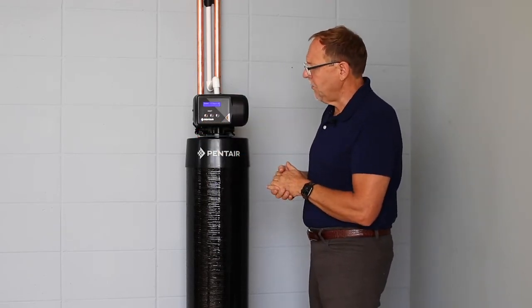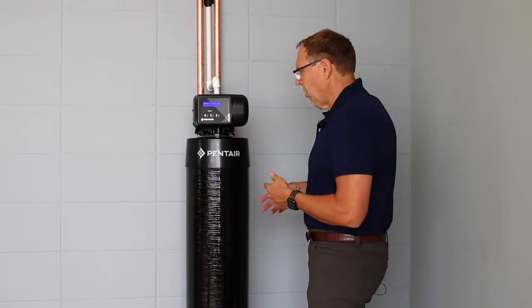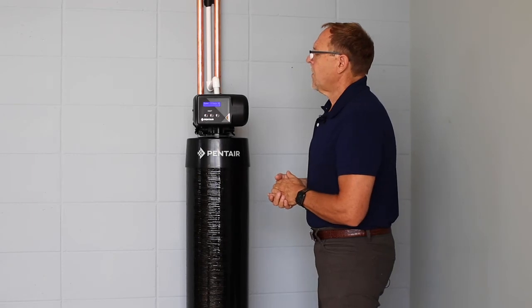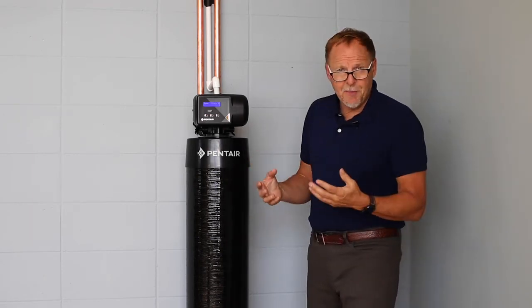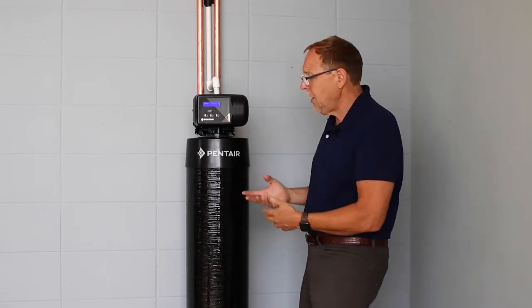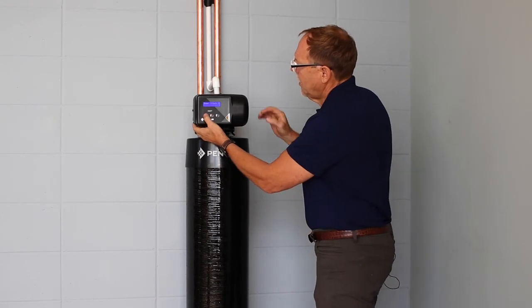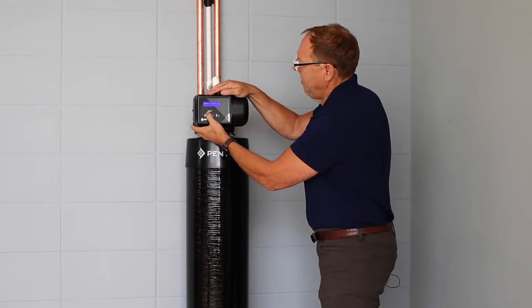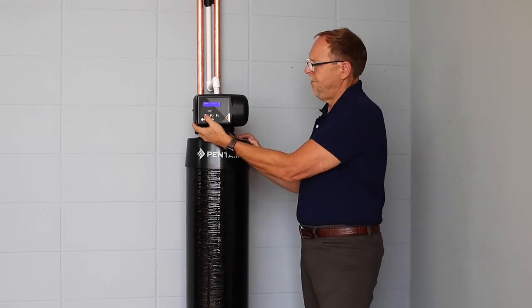And at that cycle, now it's just downflow rinsing, and you can continue to rinse the system, get all the air out, and then you're going to bring it back to home. Again, with backwashing filters, there's not much to it. It's simply backwashing to clean, and then downflow rinse to finish off. And then once it gets to there, it's only for 3 minutes in fast rinse, and then we'll walk it home.